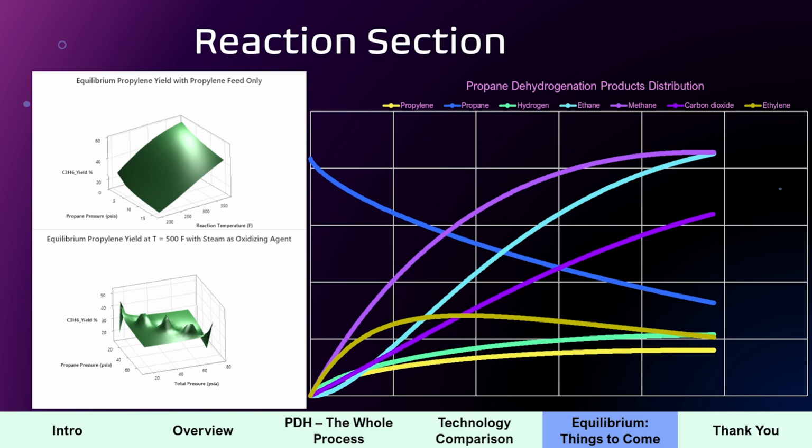You might actually find out from the get-go, oh my goodness, thermodynamically speaking, this new temperature domain, based on the mixture of the products that has been validated in the lab, is now telling me that if I operate at these temperatures, not those extreme temperatures previously known to us, the yield, or the selectivity, is already maximized. Now the catalyst only needs to focus on conversion. It doesn't need to focus on conversion and selectivity.